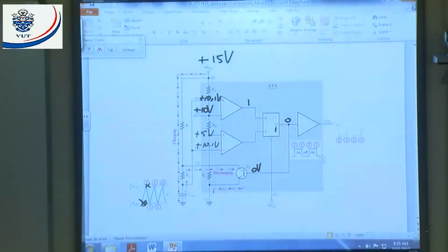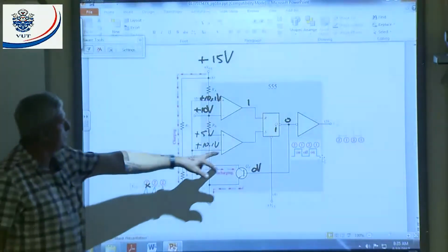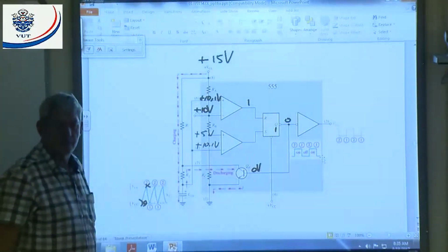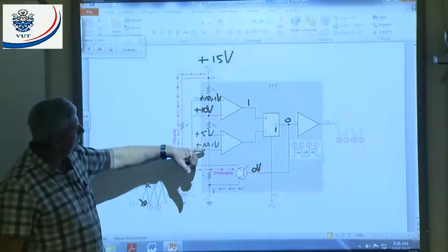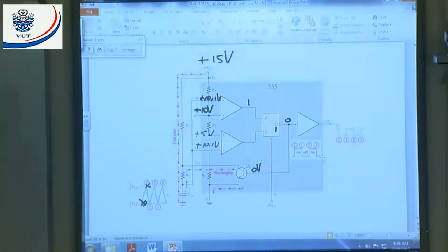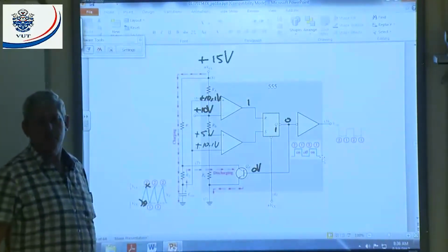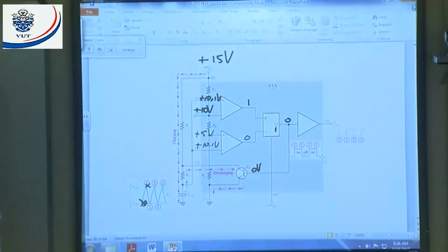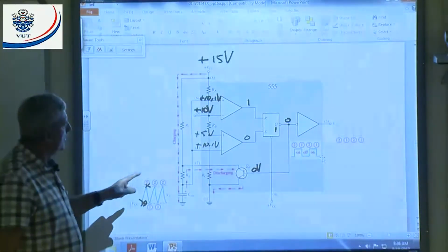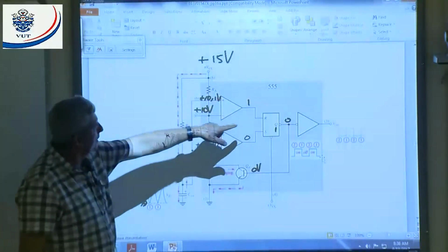10,1 volt is positive with respect to 5. That means what will that output be? What will the output be of the bottom comparator? Listen, I got 5 volts there, I got 10,1 volts there. What is 10,1 volts with respect to 5? It's positive, all right. Positive at my inverting input will give me what? All right. You with me? All right, now, what are we going to do? We're going to basically, due to that, we're going to reset the flip-flop.